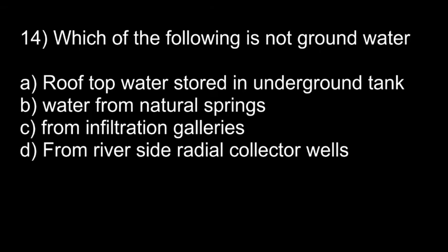Gravity springs are due to an exposed water table. A surface spring is formed when an aquifer is exposed in a valley against a vertical cut. In a shallow spring, water is collected by forming reservoirs. The next case is artesian or deep-seated spring. In an artesian spring, water flows out automatically through two impervious strata.